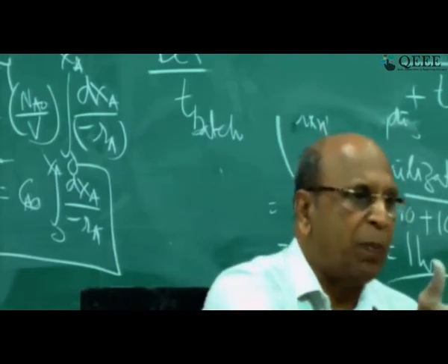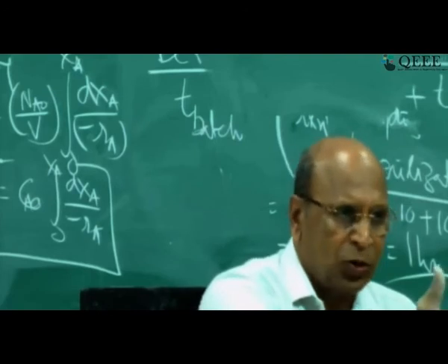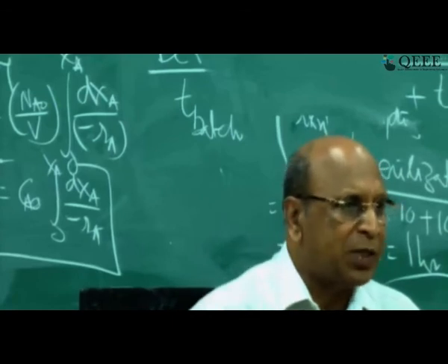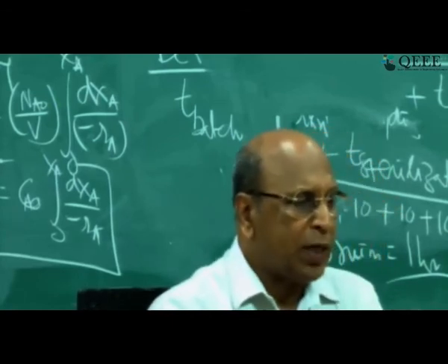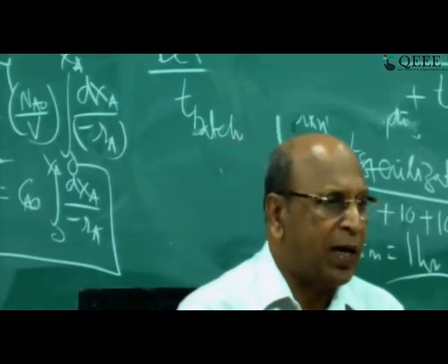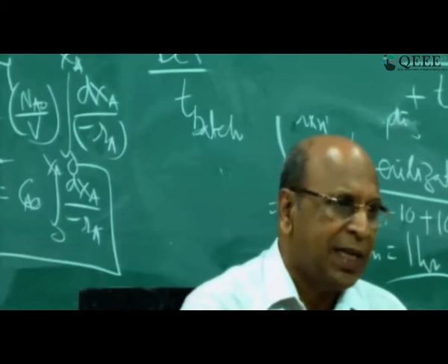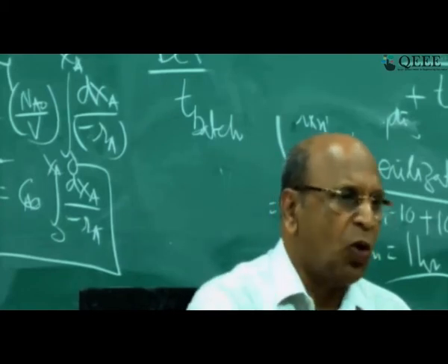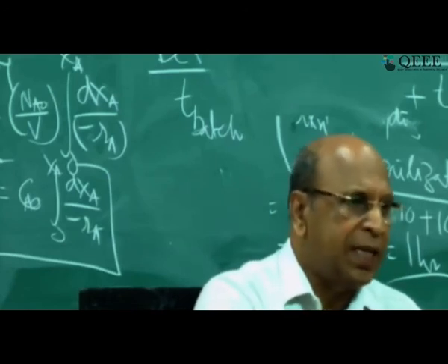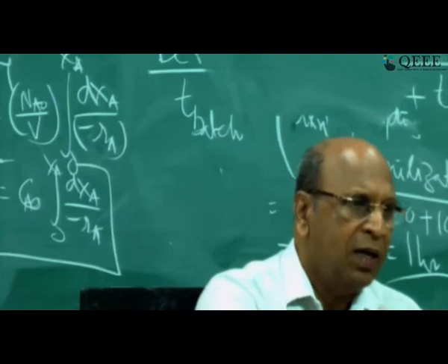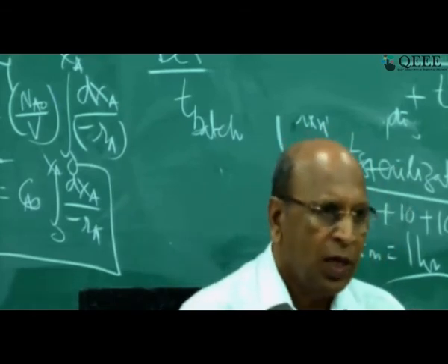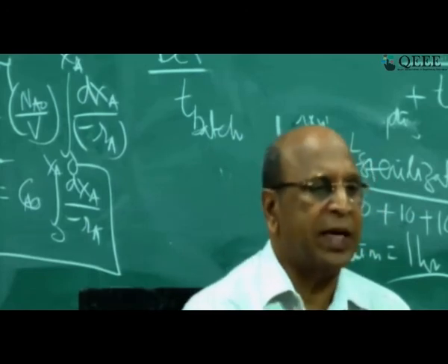One of the biochemical reaction examples, this is a good question because I can answer so many things here, is the wastewater treatment plant. Even yesterday I was telling you about that. Why is the wastewater treatment plant so big? The residence time required for the reaction is very large. The reason is biochemical reaction is very slow. That is why most of the time in biochemical engineering they use either batch reactor or chemostat, which is nothing but mixed flow reactor, where you can use 8 hours, 10 hours, 20 hours residence time.